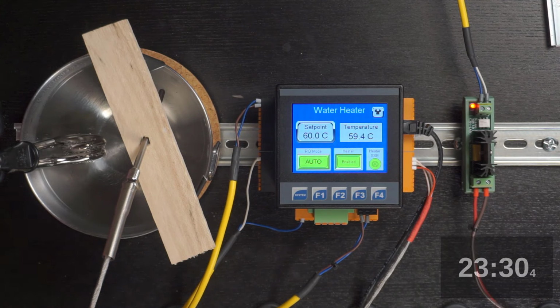Okay, so about 0.75 probably. I saw one little bit of 0.8 below the set point there. So it looks like, at this stage at least, we're within about 1.5 degrees Celsius, pretty well centered around the set point. We'll watch it for a while and see how it does.